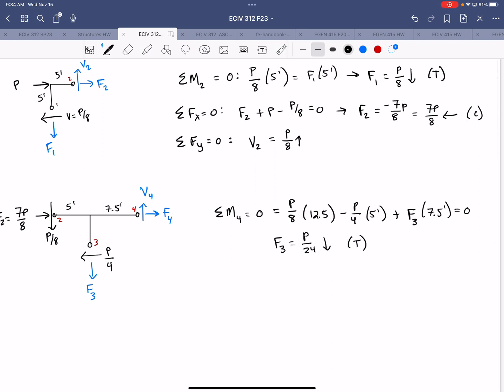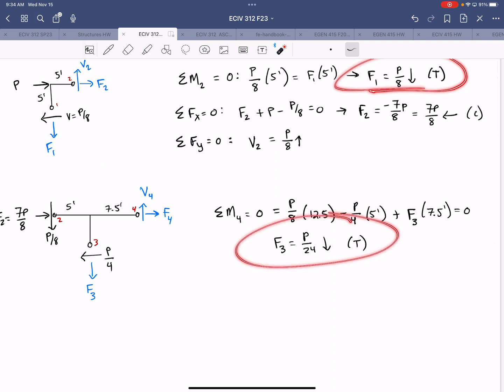All right, so this column is also in tension, but a smaller force, right? So that also makes sense, right? That the force will be smaller for the inside columns, the axial force. The exterior columns should be expected to take the greatest axial load in resisting that lateral force, right? Resisting that overturning.